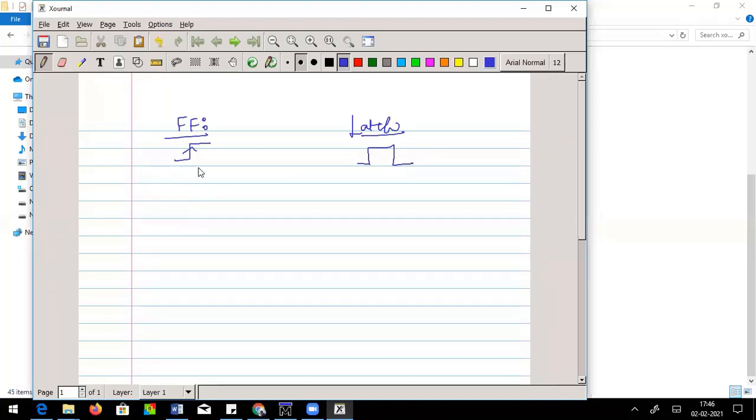What I mean to say is, say this is your flip flop, this is your D input, and this is your Q output, and of course you can have clock. Whenever my clock moves from 0 to 1, exactly at this instant, whatever is there in D will be passed on to the Q. How do I model this?